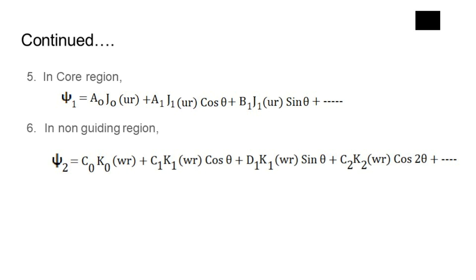Then we choose some number of matching points, for example 28 matching points, of which 22 are on the spiral and 6 are on the straight line, with their coordinates as rho k, psi k, where k is equal to 1, 2, 3, and so on. These points describe the general shape of the cross-section boundary formed by the spiral. For greater accuracy, we should take a very large number of points on the boundary of the waveguide. But for the sake of convenience in the calculation, we take here, for example, 28 points. If we take more points, naturally we get more accuracy. However, it gives a reasonable result.